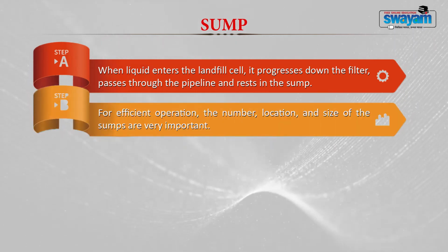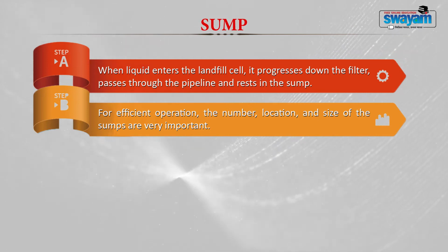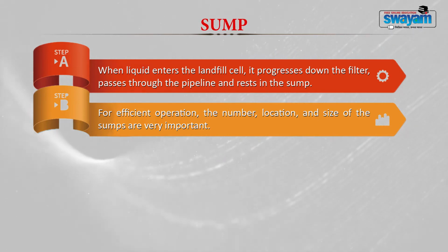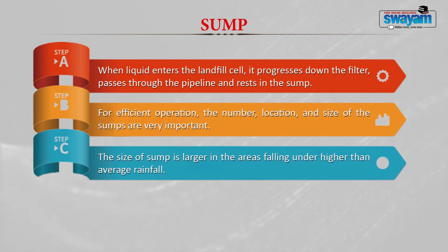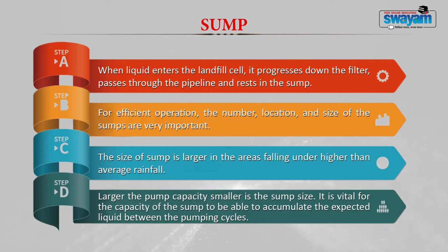Now, for efficient operation, the number, location and size of the sumps is very important. The size of the sump will always be larger in areas where you receive a very high amount of rainfall. Now, the larger the pump capacity, the smaller should be your sump size. It is vital that your sump should be designed in such a way that it accumulates the expected amount of liquid that is being pumped from the leachate collection system.